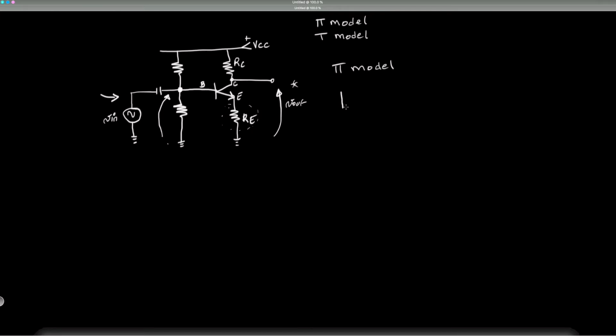So let's redraw our power source, or the feeder signal. This capacitor here will be considered a short at a certain frequency and capacitance value, where XC here is almost 0 at the operating frequency that you want this stage to work.